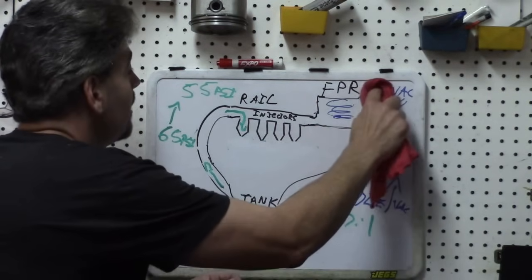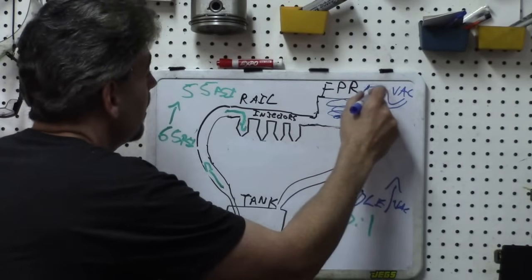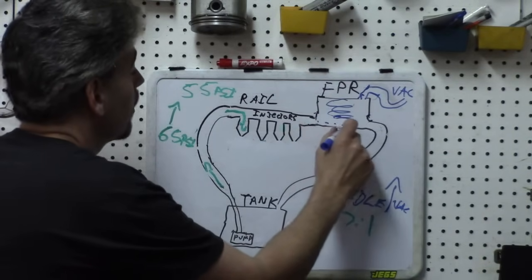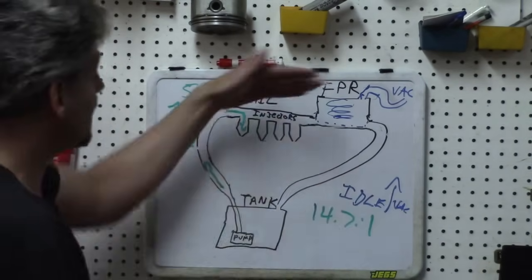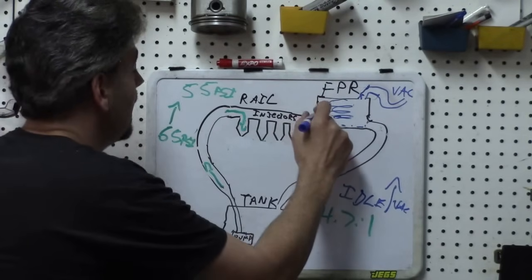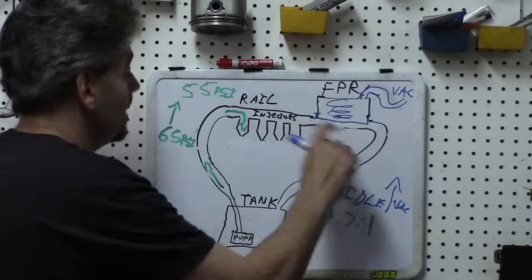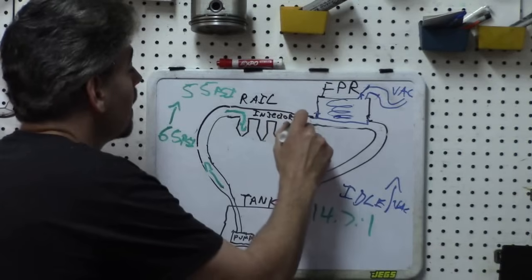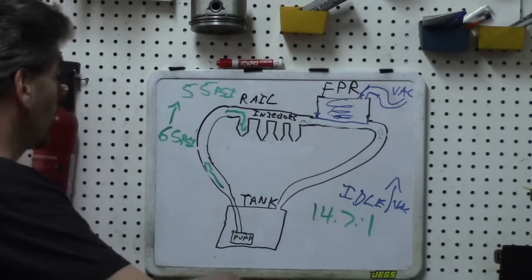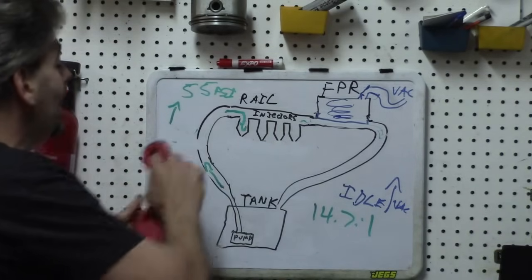All right, let's do this. Let's go ahead and at idle, we reconnect the hose. What's that going to do to our diaphragm? When we reconnect the hose, it's going to suck up and counter the spring and pull that diaphragm back to its original condition, allowing that flow to increase through the return. And of course, we will go back to our usual PSI at idle.